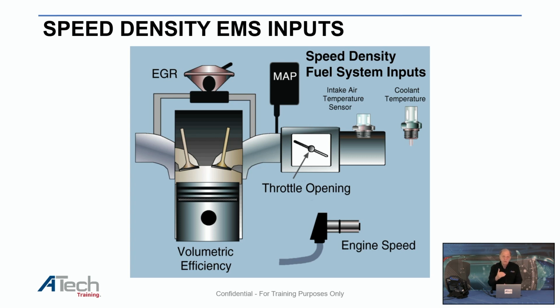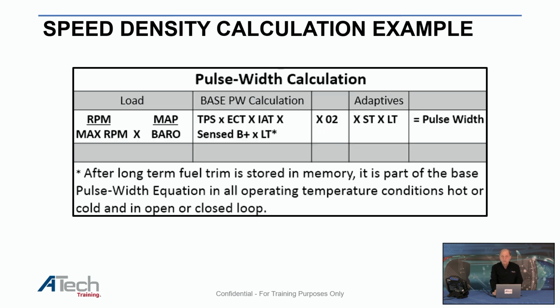For you guys that's starting to get into looking at this, if the EGR is not working correctly, it will cause a problem on the particular car, because when the EGR comes on, it's going to change the air-fuel mixture. They're going to back off the fuel trim on the vehicle at that point. So a lot of times EGR can cause an issue on these particular cars. Let's go over and look at this calculation.